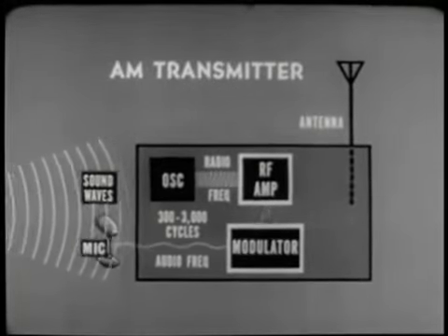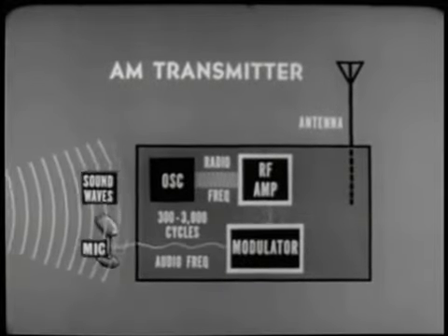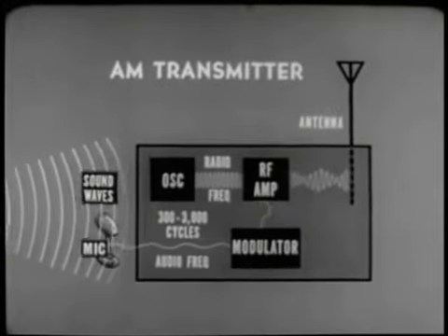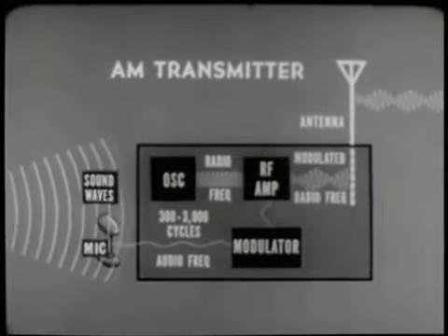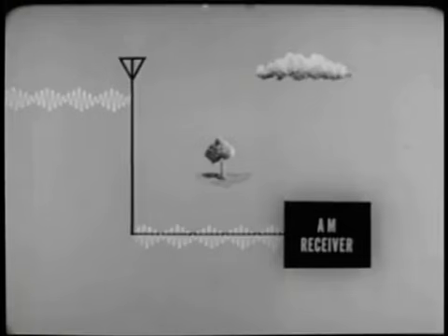By means of a modulator and one or more RF amplifiers, the amplitude variations of the audio signal and the radio frequency carrier are combined. Now the intelligence takes the form of amplitude variations in the carrier. The amplitude modulated RF carrier is fed to the antenna, from which it is radiated through space to the receiving